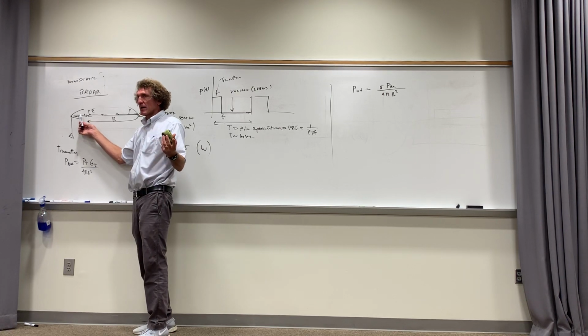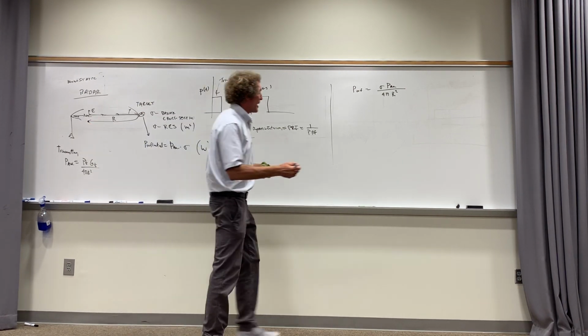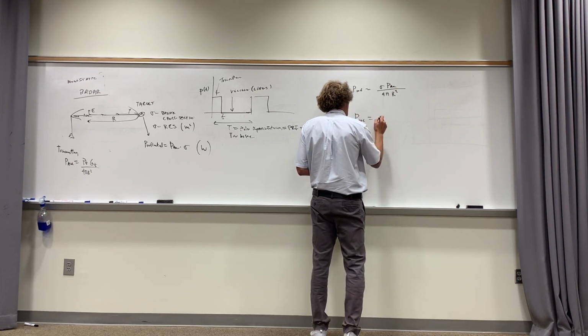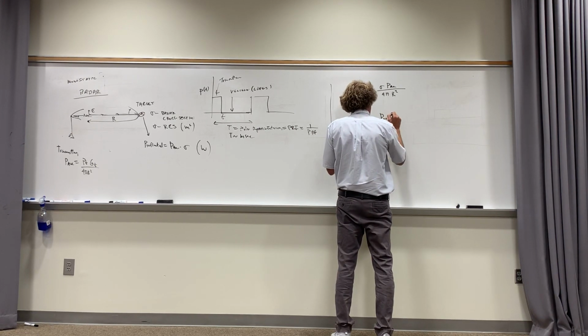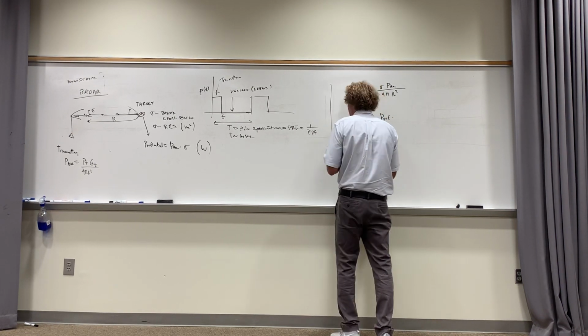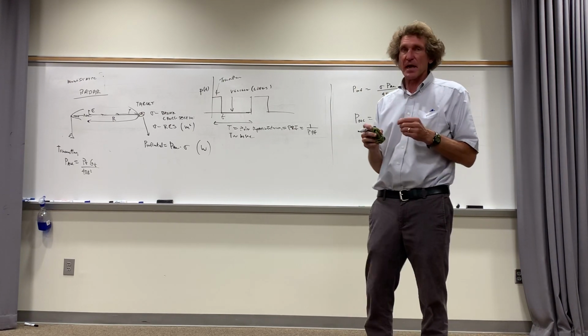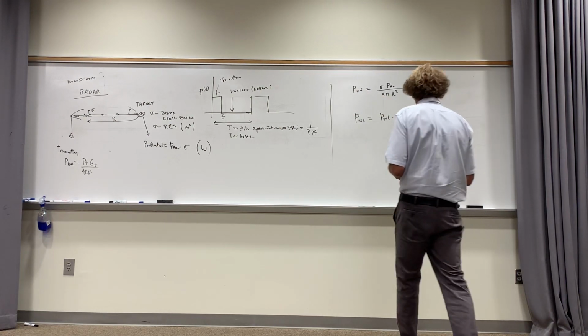Now we need to find the amount of power the antenna catches. And that means how electrically big it is, or the area, or aperture. So now we can say that the power received by the antenna would be equal to this power reflected times the area. Do you remember what the aperture, or the area of the antenna, is in terms of gain? Anybody? Lambda squared G over. That's exactly right.